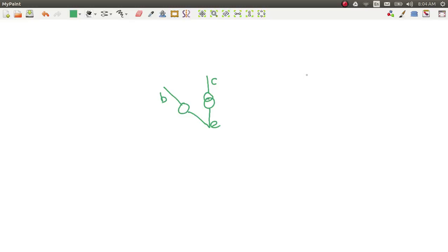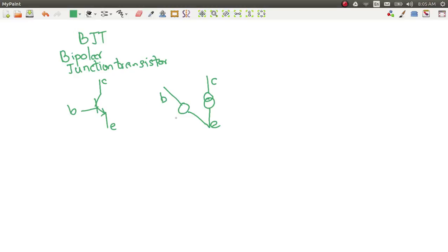If we look at the ideal model for the bipolar junction transistor, and I have added it in the site, then we see that we have a nullator here, and the nullator is basically represented by the 0. This says that the current through the nullator is 0, and the voltage across the nullator is 0, and here I and V can be anything.